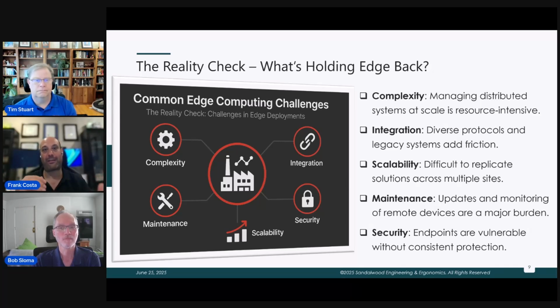So there's a lot of work that has to be done on the, we'll call it the left side of it, where the machines are. But once that work is done, you can instantiate those rules at the edge, and then we're talking commonly to your SCADA system or your MES or your ERP. Ideally, you want all those major systems talking in the same language, which again can be facilitated by a CDM, or what's known as a common data model.